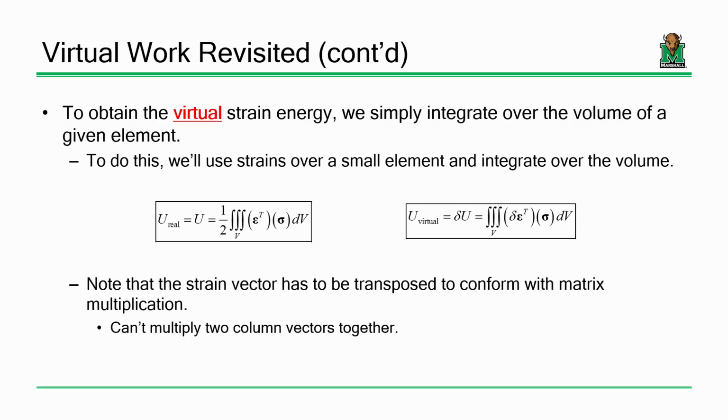What's different? Here I'm talking about stresses and strains. Before, it was just the load times the displacement. Now it's the stress times the strain, but that's infinitesimal, so I've got to integrate over the volume. That's what I've got here. This definition is no different than what we had before. It's just expressed with a little more finesse, I guess I could say. Is that all right? Okay.